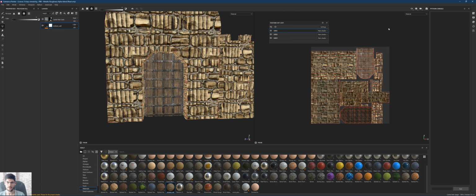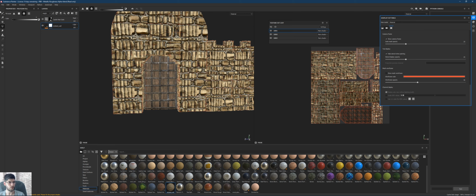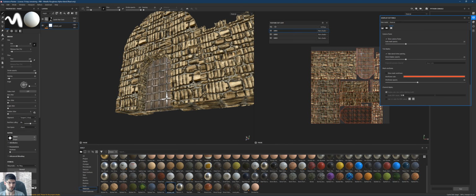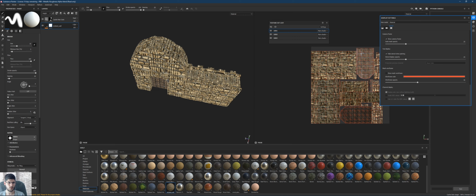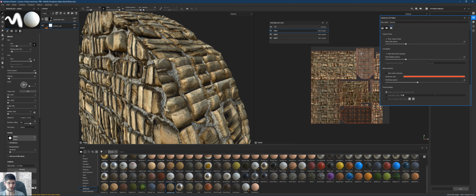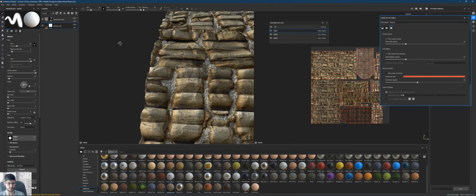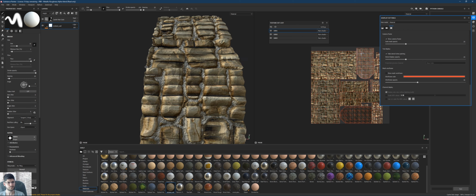Okay, so let's also go and deactivate the wireframe because it's really getting on my oh no, sorry, the wireframe is only active because I've got a black mask active. Okay, right, so you can notice over here where we've got the seams, there are a bit of problems with the elements, so you can see how the displacement map is breaking the geometry a little bit.